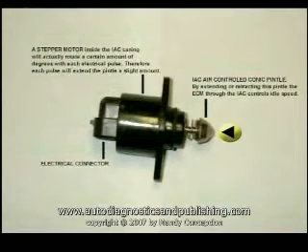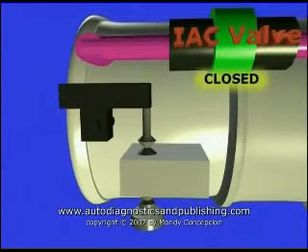The IAC pintle, or motor valve, controls the air past the throttle plates, and it may be connected to the ECM by 4 wires. There are different types of IAC motors, but the principle is the same: to simply let a measured amount of air pass the throttle plates. The IAC has to be completely closed during a minimum air rate adjustment.